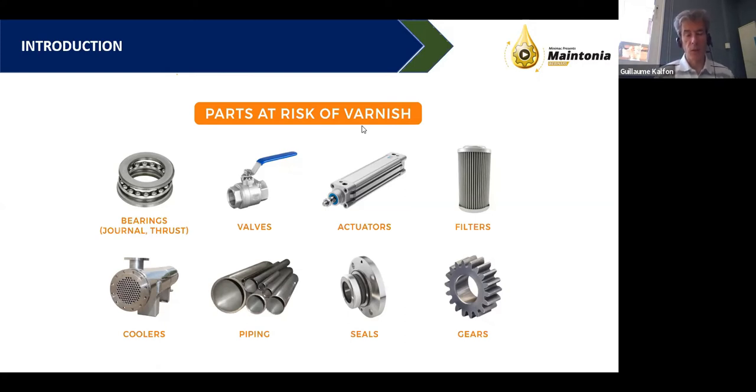So we can see that controlling the equipment becomes difficult and then becomes impossible. In filters, it can accumulate. It can look like a gooey deposit, sticky, gooey, shiny deposit that can clog the filter, and you may start to see filters that need replacing too often, more and more often.